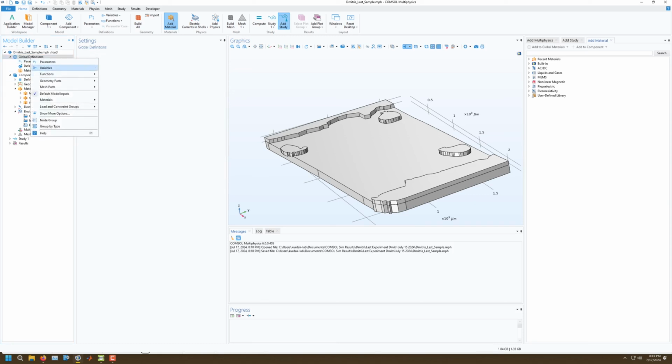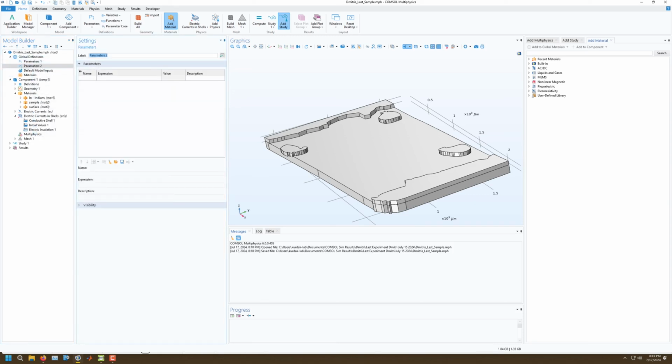I'm going to make a new set of parameters so I don't confuse myself. And I'm going to call these the 3D resistivities. And if spelling mattered, it sure would. So now I'm going to just do PSXX3D. This is going to be the 3D surface XX resistivity. And this is going to be equal to the surface resistivity divided by the thickness. Let me remember what that is. Yeah, it was 1 nanometer.